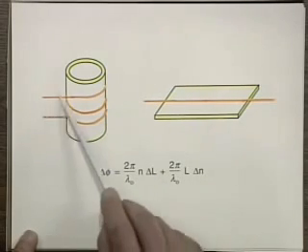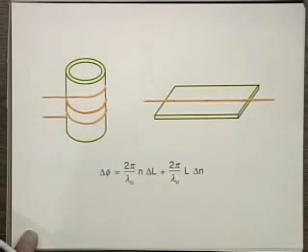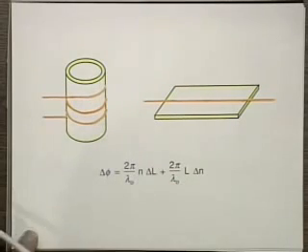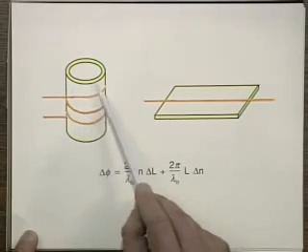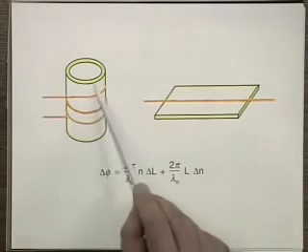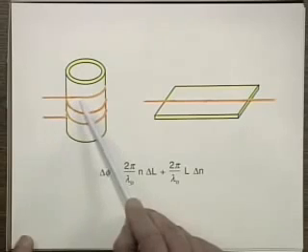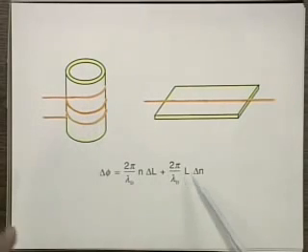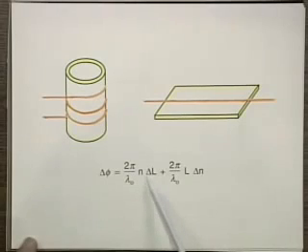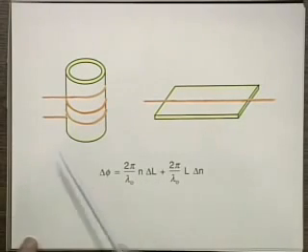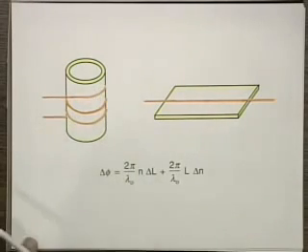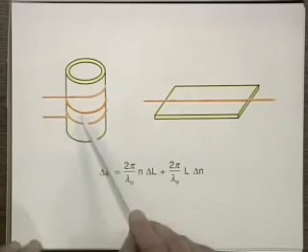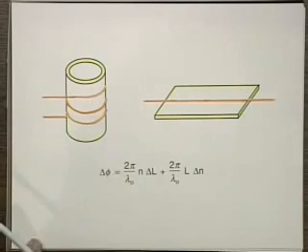One way of doing this is to take the fiber and wrap it around a piezoelectric crystal. If we put a voltage between the inside and the outer surfaces of this crystal, then we can change the diameter of this cylinder, and in this way we can change the physical length of the fiber, or by stressing it, essentially could change also the index. But whatever, you get a change in the phase of the light propagating by applying a voltage, either a DC voltage or sinusoidal voltage, to this piezoelectric cylinder.